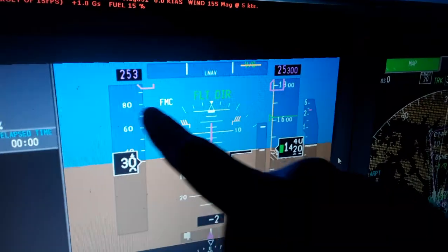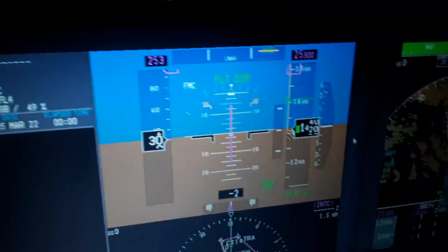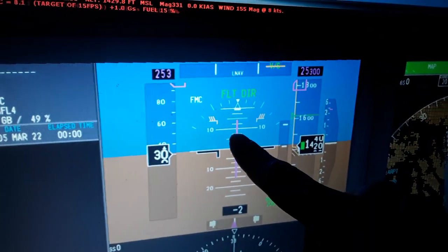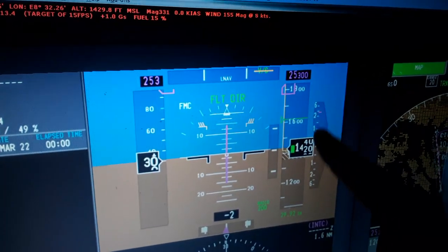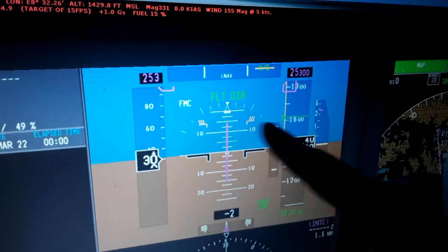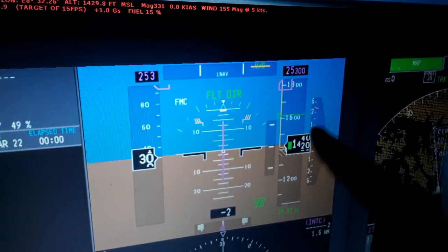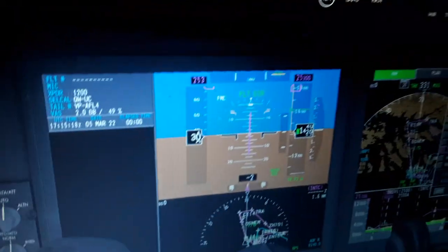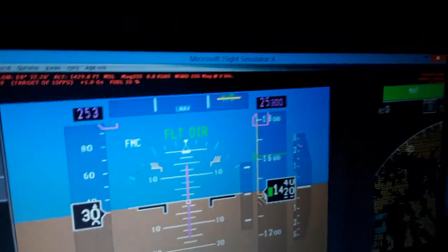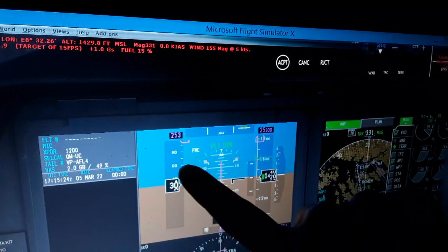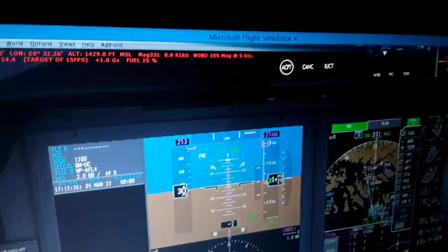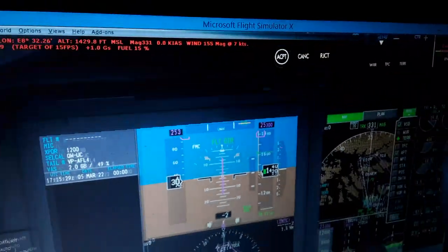So you have to pay attention in the air when you fly. You don't know really if the aircraft is pitching up, but it might be falling down. So you have to pay attention to both the pitch attitude and the vertical rate of climb and descent, and also the airspeed, radio altitude above the ground level, and the bank angle here in degrees, how steep bank angles you make when you turn in flight with roll.